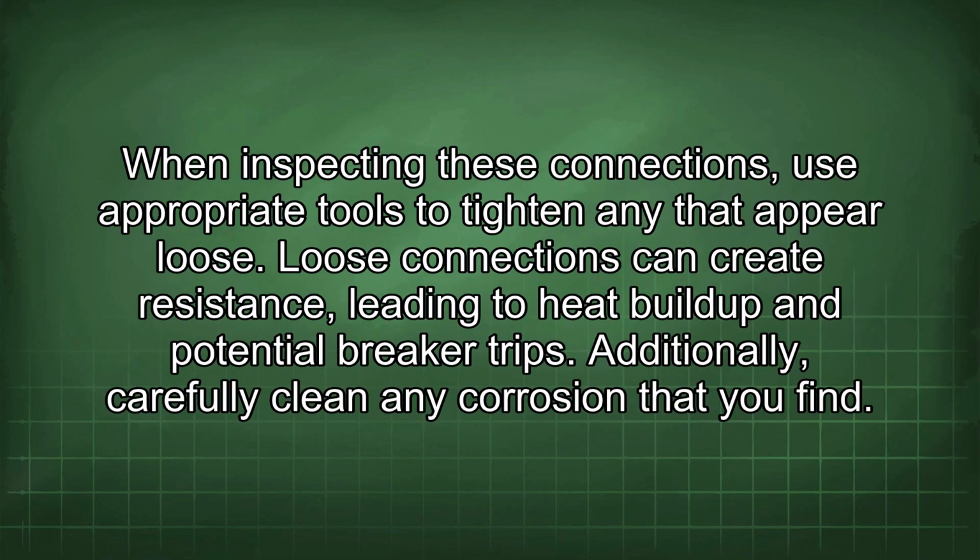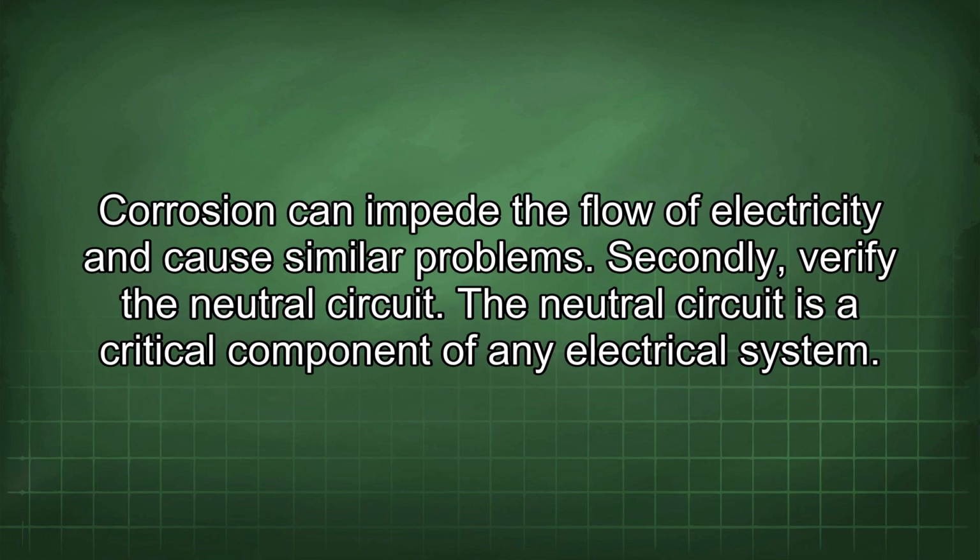When inspecting these connections, use appropriate tools to tighten any that appear loose. Loose connections can create resistance, leading to heat buildup and potential breaker trips. Additionally, carefully clean any corrosion that you find. Corrosion can impede the flow of electricity and cause similar problems.